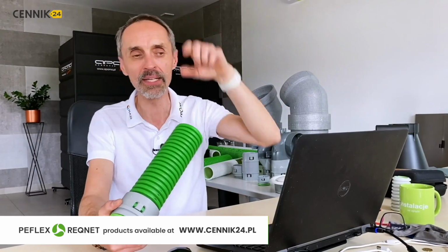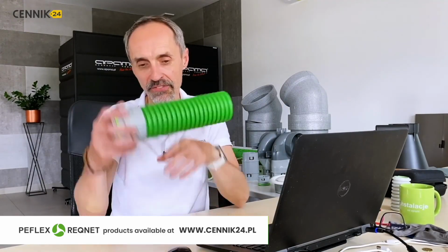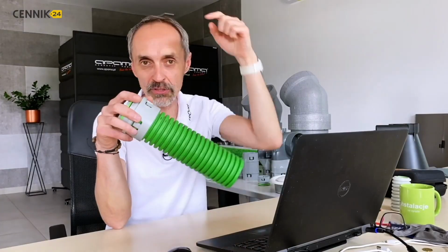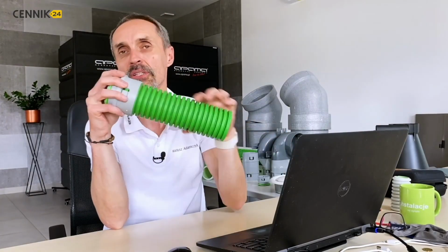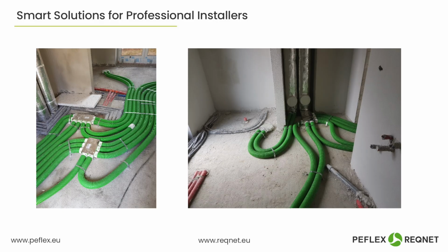So it's better to plan this properly in advance, to anticipate things so that the installations avoid each other. And if they do have to cross at the same height, then, for example, you could make a notch in one, or change the diameter, or adjust the height.